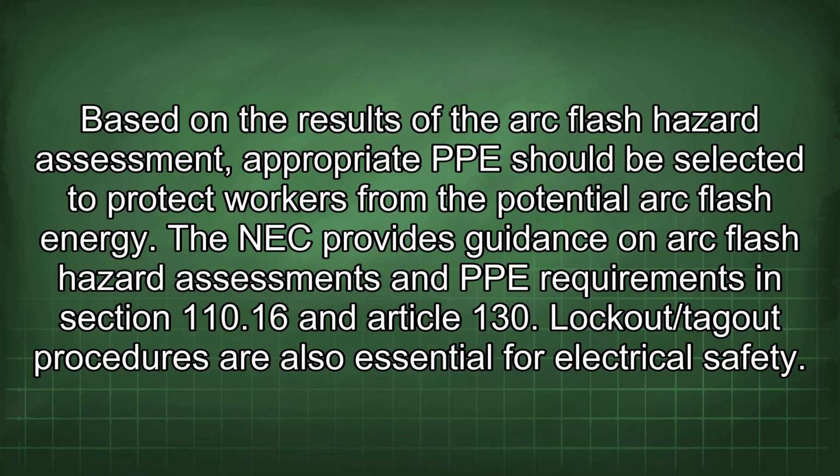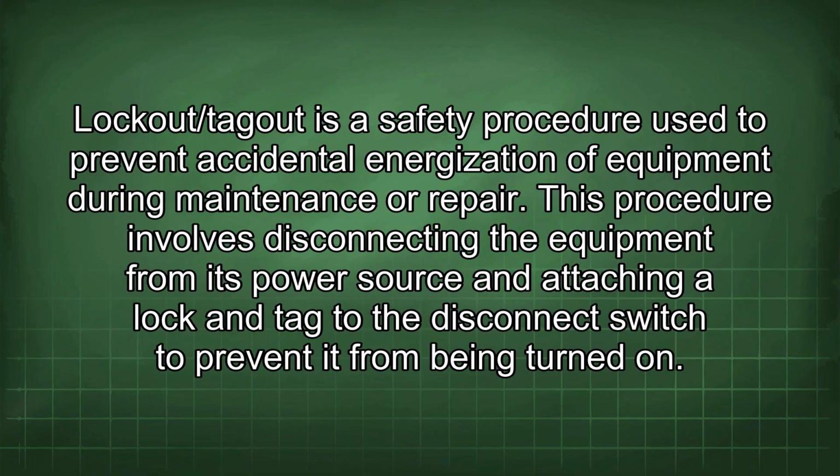Based on the results of the arc flash hazard assessment, appropriate PPE should be selected to protect workers from the potential arc flash energy. The NEC provides guidance on arc flash hazard assessments and PPE requirements in Section 110.16 and Article 130. Lockout/tagout procedures are also essential for electrical safety.